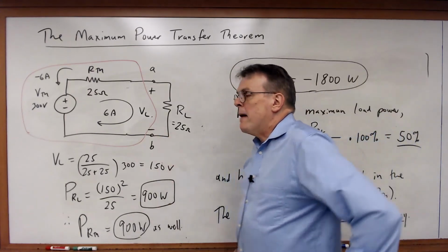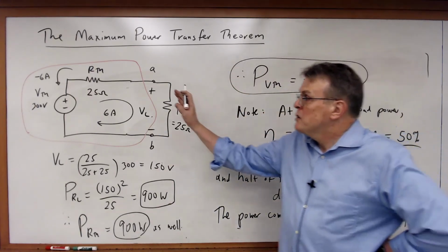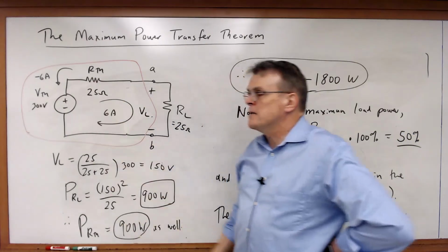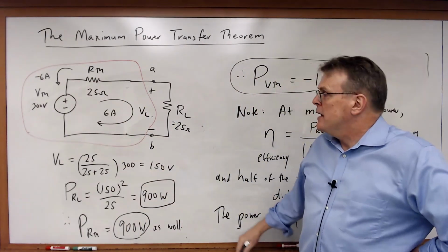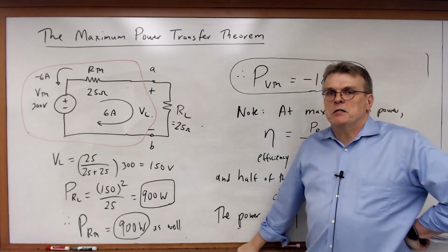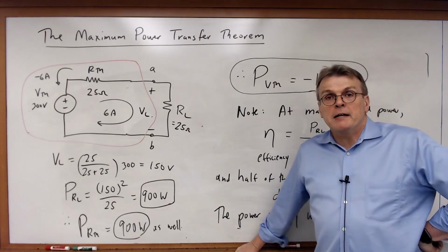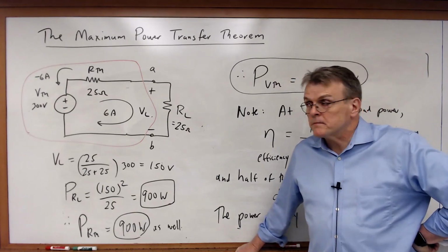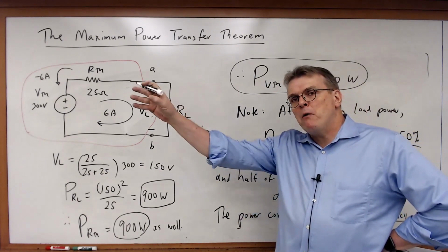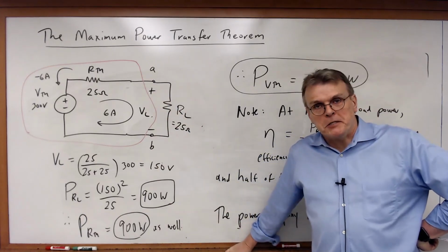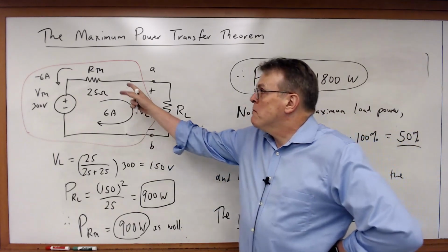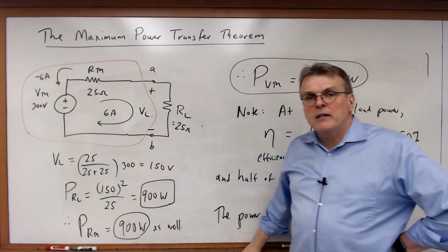So really, the power company prefers to try to change this equation. And what the power company tries to do is both minimize RTH, the Thevenin resistance, and also find a way to effectively increase the value of the load resistance. And this is done through techniques using components called transformers. And you will also see, for example, that the power company will transmit power over long distances at very, very high voltages. And it turns out the reason for that is, once again, to allow them to minimize the power that is lost in that Thevenin equivalent resistance.